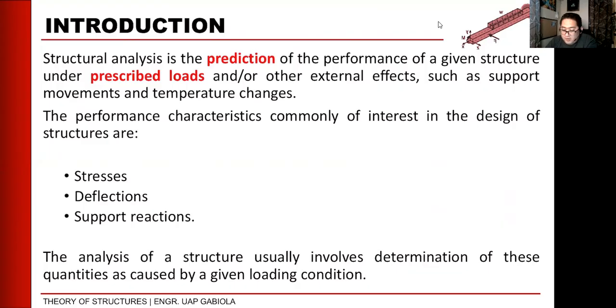So what will be its behavior? And then lastly, our support reaction is the force exerted on the supporting element, on the member that we are designing. So, say for example, from the beam, the beam will transfer its forces to the column. So if we want to simplify the design, what would be the forces at the ends of the beam that will be transferred or carried by the columns so that they will be transferred to our foundation.